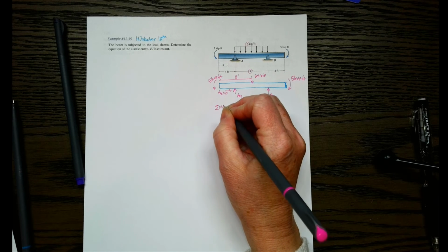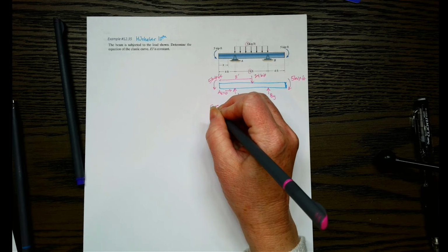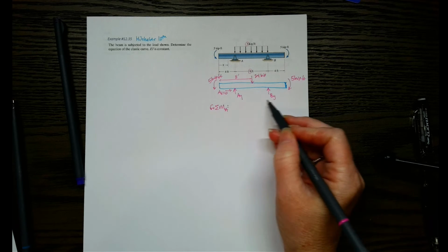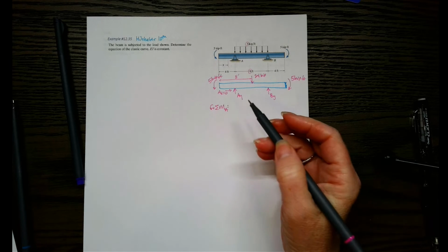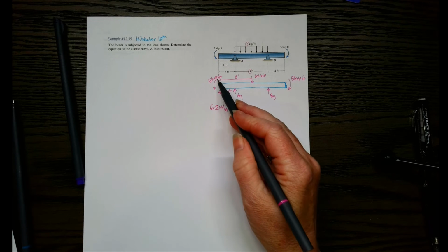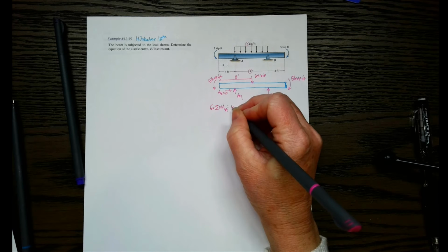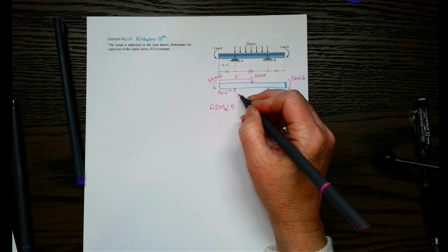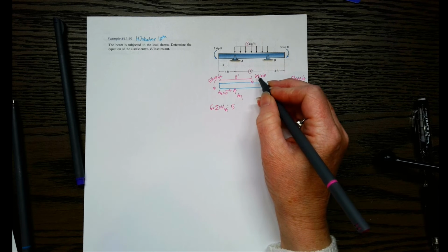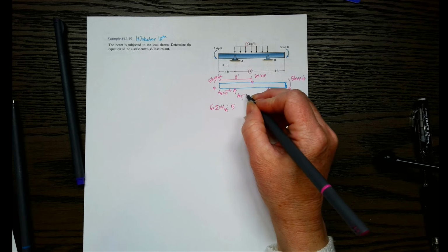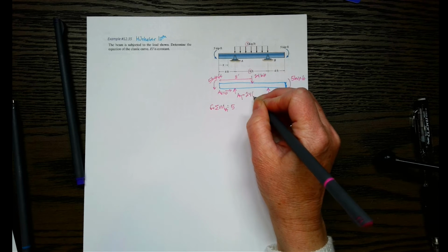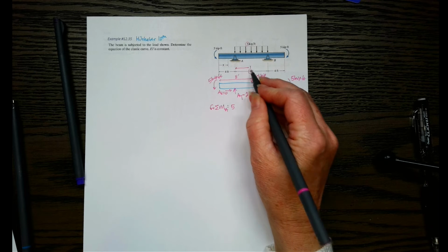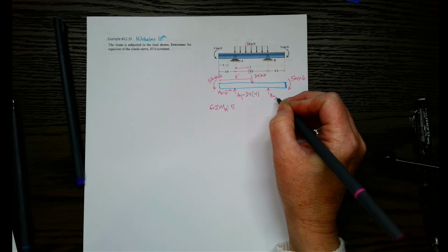So let's just do one of the equations. Let's just do the moment equation about point A, just to show you that it is 12 in case you're not seeing it yet. Okay, so counterclockwise is positive. That means we're going to have a positive 5 here. And this is point A right here, right? So no moment created by AY because it goes through A. This one does create a moment. It's going to be negative because it's clockwise. And that'll be 24. Distance is basically from here to here. So that's 4.